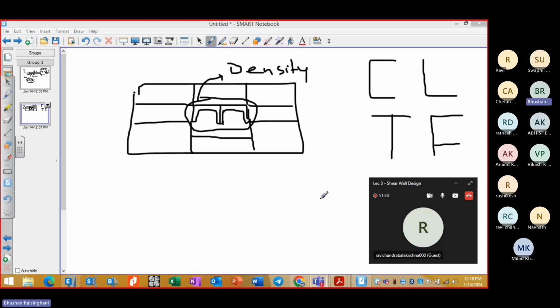So you have to give heavy columns, or in that way you should consider some amount of forces, at the minimum nominal forces, like the 25% we have for the dual system, right? So our frame takes 25%, so you at least assume 25% will come on the staircase and design your column accordingly. Then also it can help.